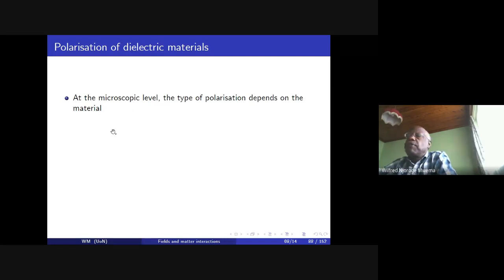This is different from wave polarization, where we are just describing the electric field intensity vector in a wave as time progresses at a fixed point in space. Here we are talking about material polarization, where the charge distribution on the molecules forming the material are displaced from each other such that we have an induced electric dipole.